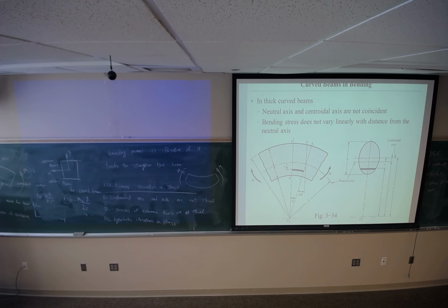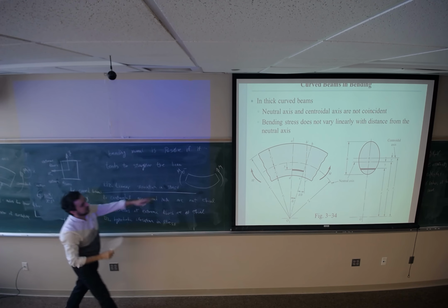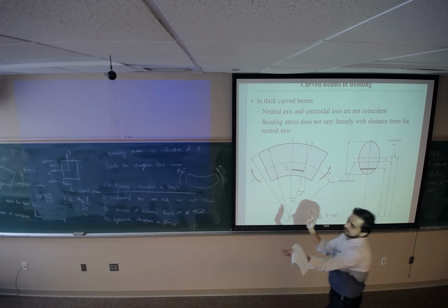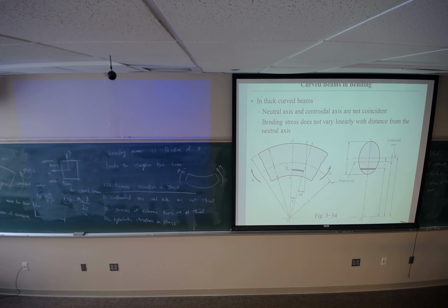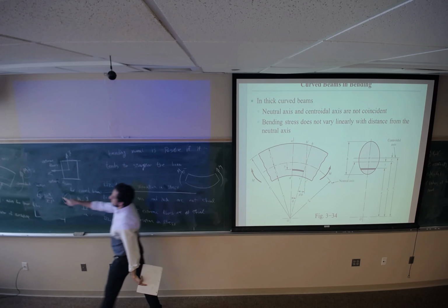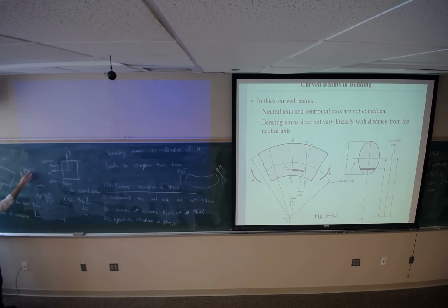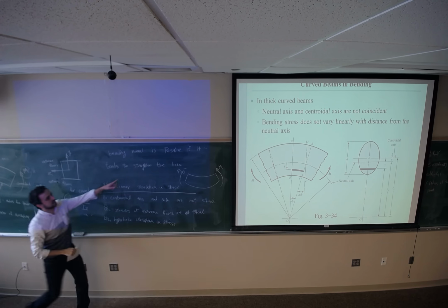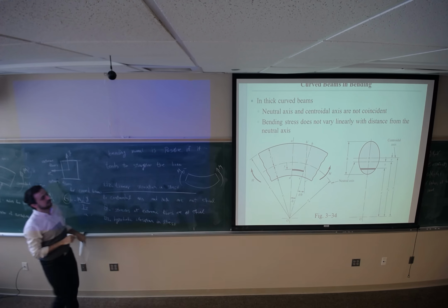This bending moment, I didn't change the direction of the beam and the direction of the moment. I just changed the curvature of the beam from that direction to that one. For this one, we should consider negative for the M. For this one, it should consider M as positive. So if it tends to straighten the beam, it should be positive, otherwise negative.